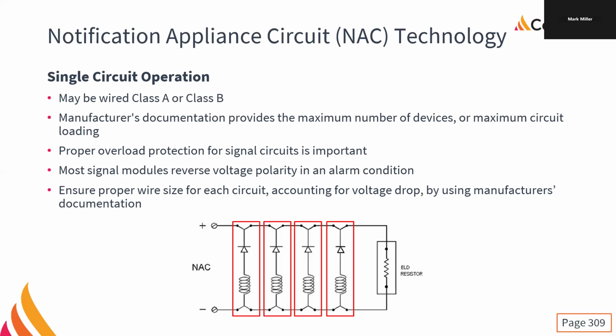So we have to make sure that we're not overloading the circuits, and we need to make sure that we have proper overload protection. There are fuses or circuit breakers built into the panels for the notification appliance circuits.